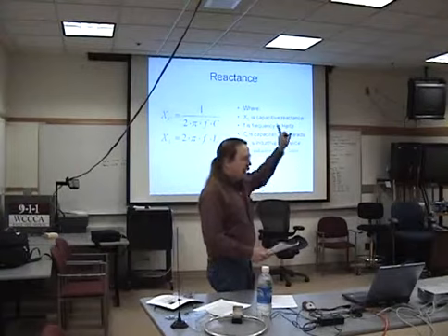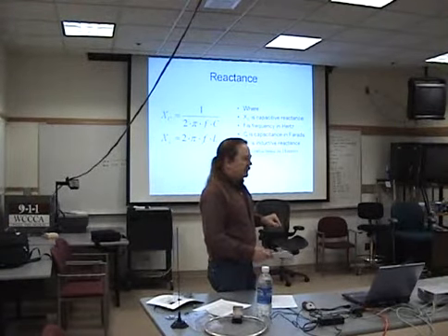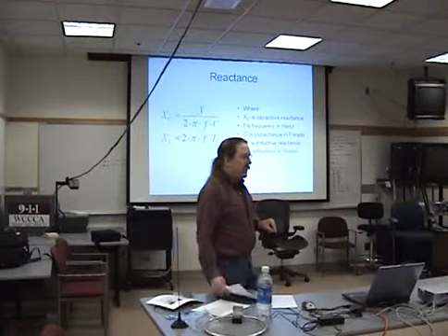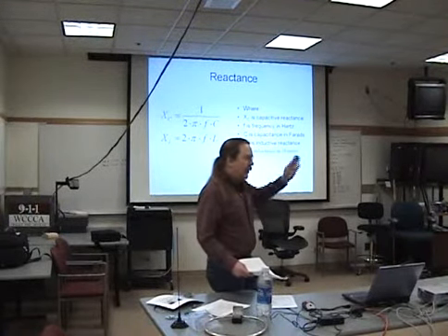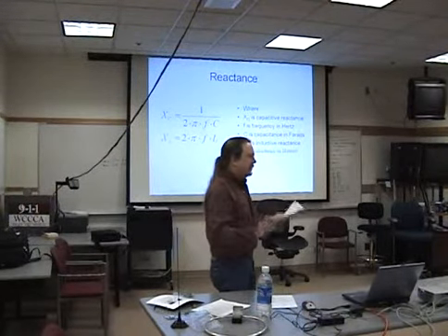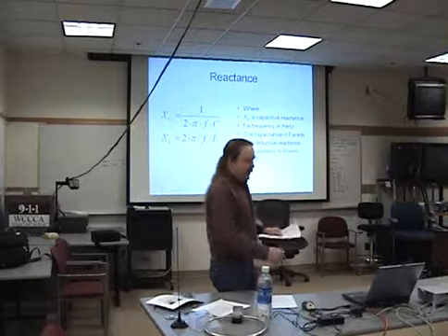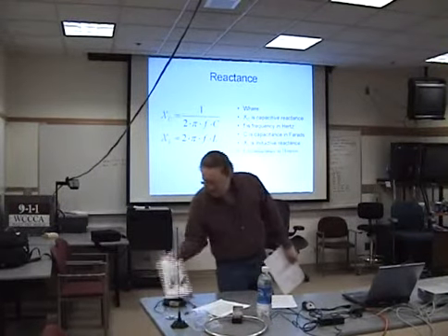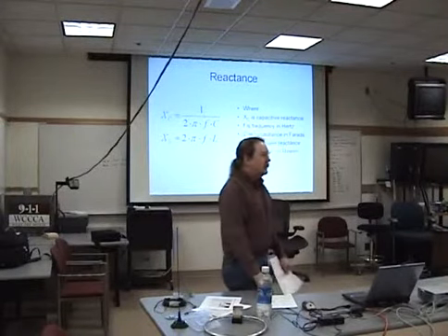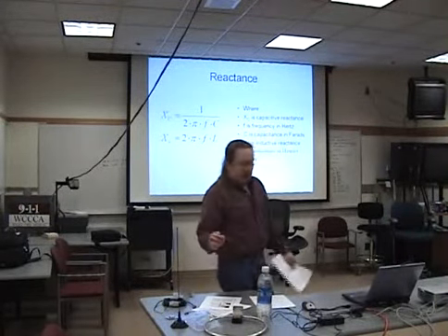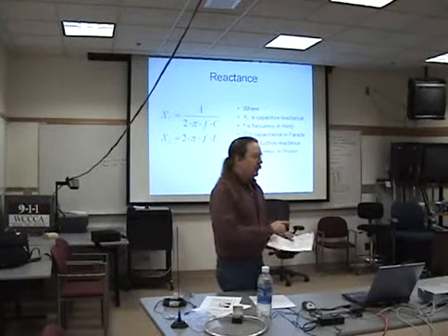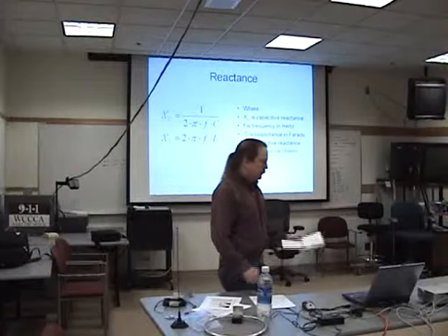And if it's positive 90 degrees. So any of you who took your extra class test, a lot of figuring out 135 degrees, there's 75 degrees, and you're going, what's going on? Well, then you get yourself one of your antenna tuners and you get rid of all the reactance in the circuit. So between your transmitter and your antenna, you have a purely resistive load. That's the ultimate goal. To figure out capacitance, or capacitive reactance and inductive reactance, here are the two formulas.